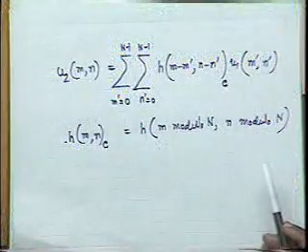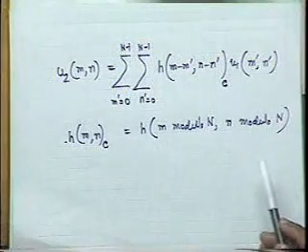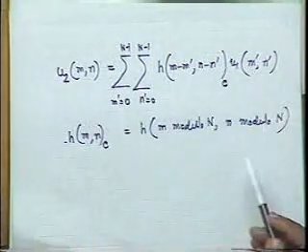Now as you clearly see over here, the order of complexity of convolution in this case is N squared. Convolution we have to do it like this. It's a bit complicated in the sense that we have to fold over the function and then sweep it over the entire range. We will see in the next class. We will spend some time first to indicate whether we need to do the convolution like this, or we can do some simplification in the frequency domain.